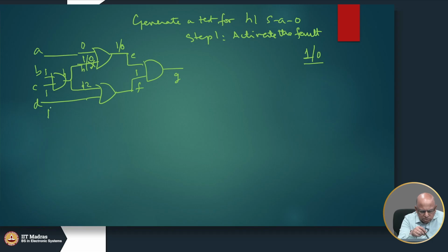Actually, see, this is x actually. We can either put a 0 or a 1, because this 1 will also cause a 1 here. Remember there is no fault on H2. So, a 1 on this will come over here, okay, and as a result this is x.